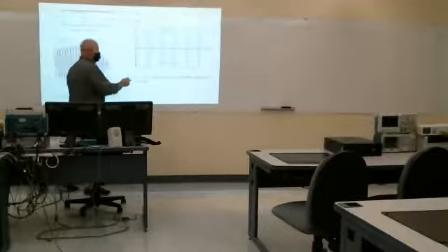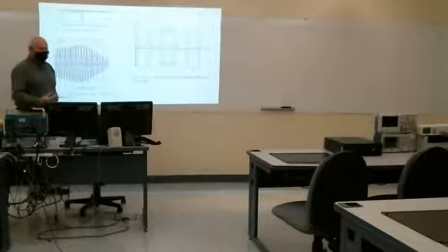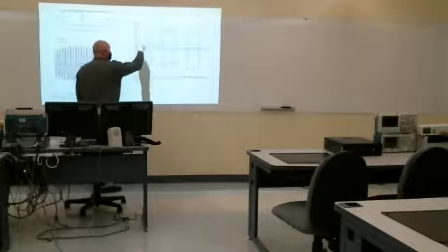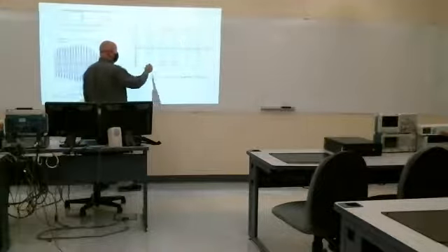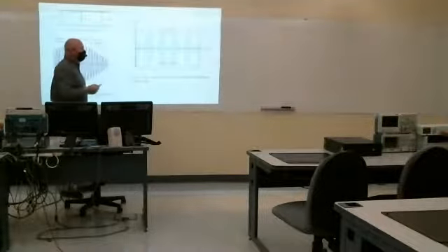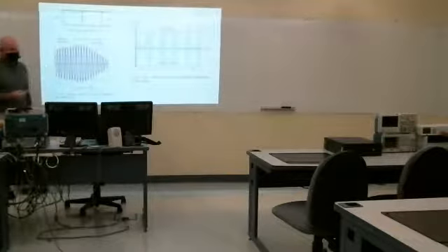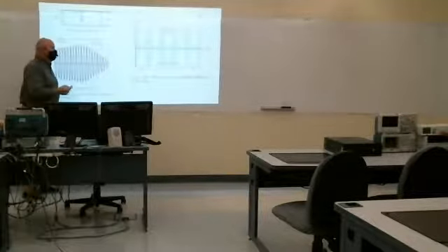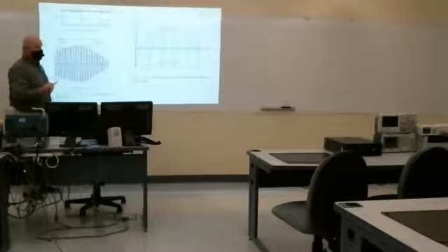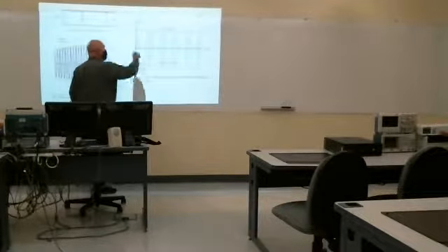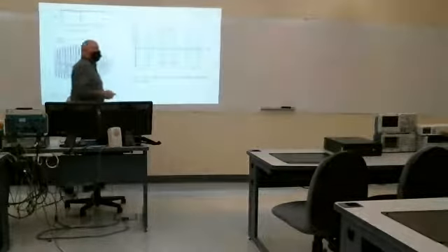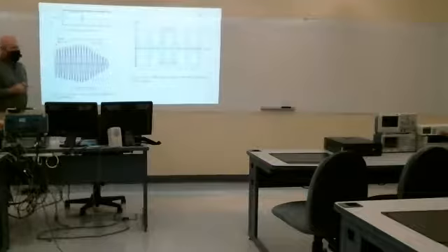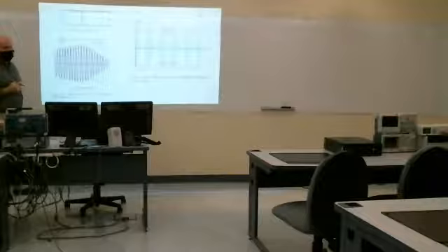This is showing a very special case of what's called tone modulation, where the low frequency message is actually a 1 kilohertz sine wave, and then on a 10 kilohertz carrier. So you could generate that in MATLAB pretty easily, actually. But one of the nice things about AM is that you can really see the low frequency message in the modulated carrier. Okay, you can see it on an oscilloscope. That's not the case with techniques like FM or phase modulation.